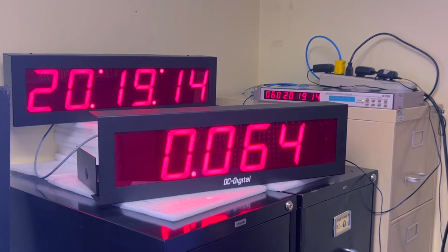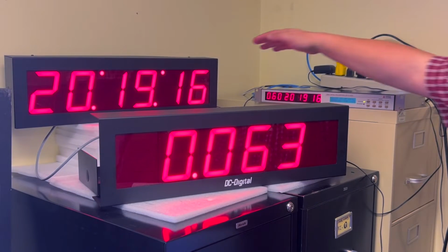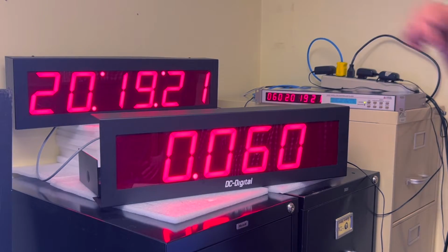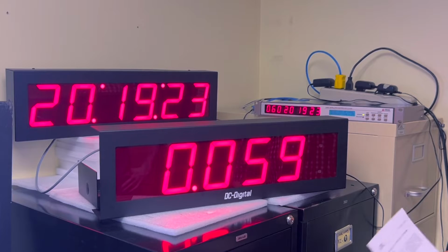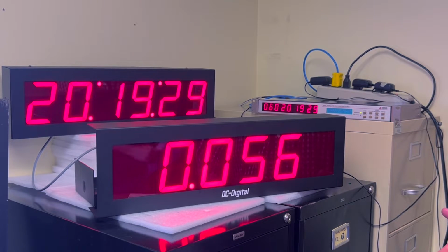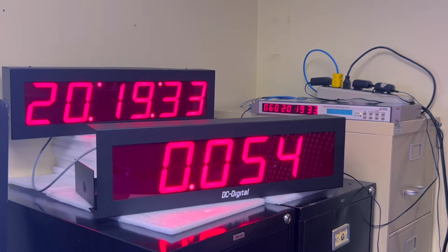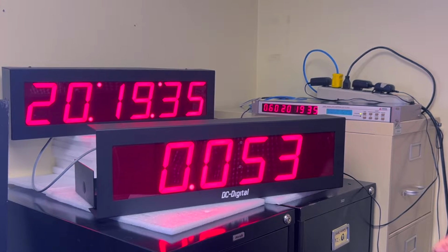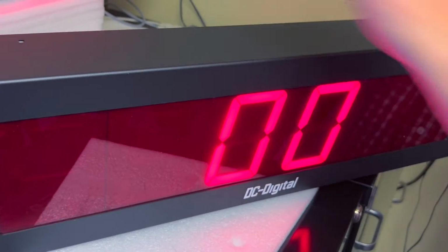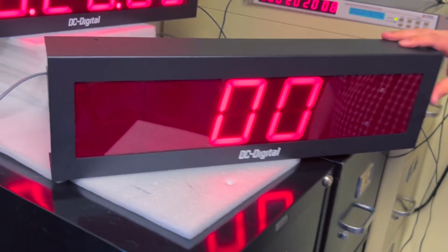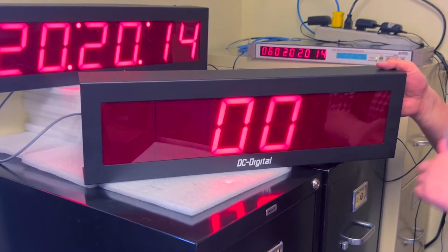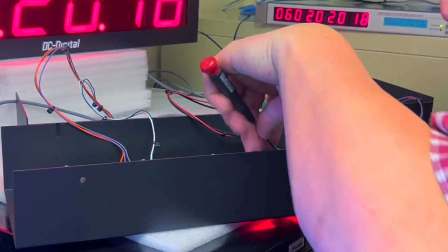Correct. So you don't have to have this one in the first position and this one in the second position. They can be swapped, interchanged, etc. Also, you don't have to have a different part number for each of those modes spelled out in the application note. For mode 11, you set the dip switches to position 1, which I'll do so now. So position 1 is out of lock. Right now we have out of lock set at 0, so it's actually displaying what our out of lock is.